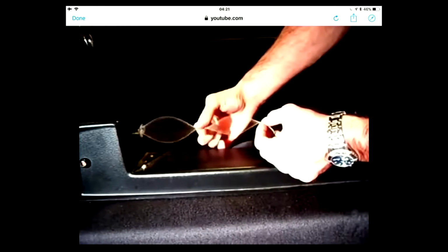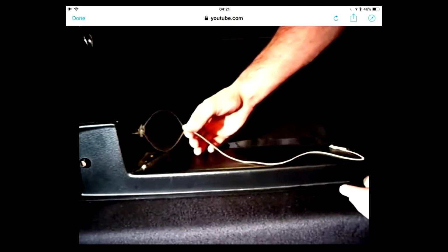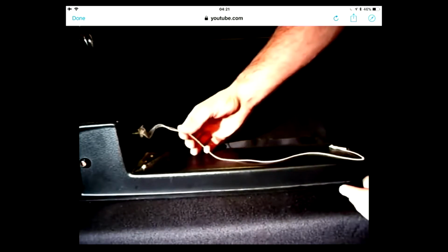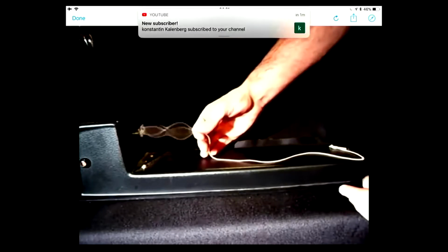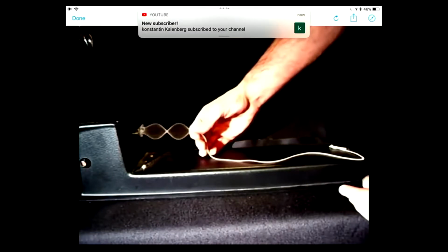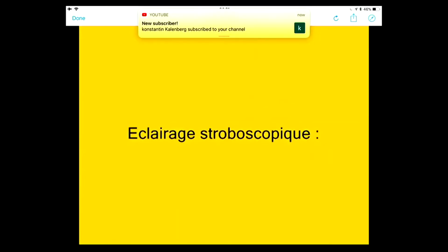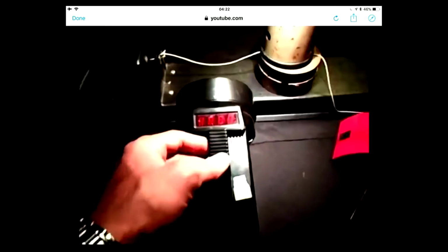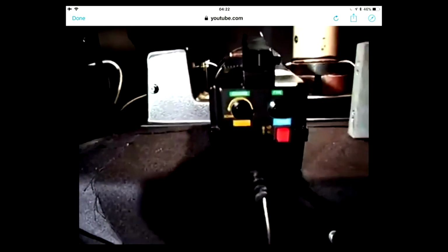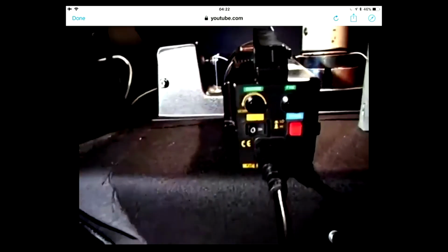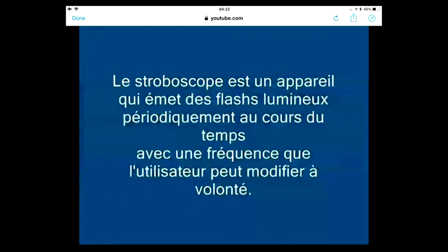So for me, the point is that there is this mode shape that determines how the string moves, how quickly it moves, and what the frequency of the vibration is. That is determined by the eigenvalue. The frequency is the imaginary part, and how it decays over time is the real part of the eigenvalue. Now, what they're doing here is not only exciting this string at a certain frequency, they will also illuminate it at a certain frequency. So look at what happens.